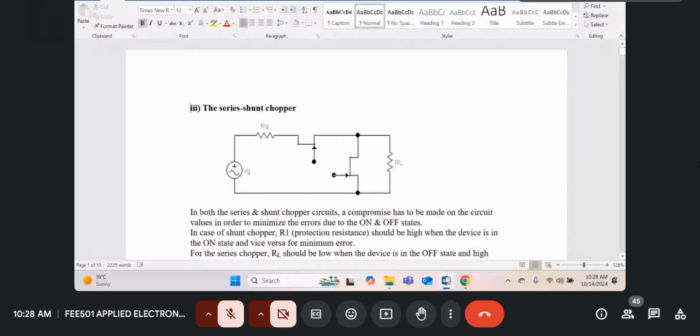Now we have another switching configuration, which is called the series shunt chopper. So in the series shunt chopper, this is how the transistors are connected. So this is the figure. You got your generator, you got your generator resistance, RG, you got your first FET over here, which is in series with the load. And then we got your second FET at the bottom over here, which is in shunt with the load. So this configuration is referred to as a series shunt chopper.